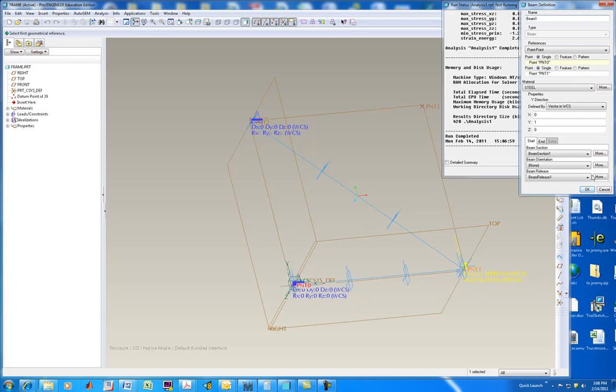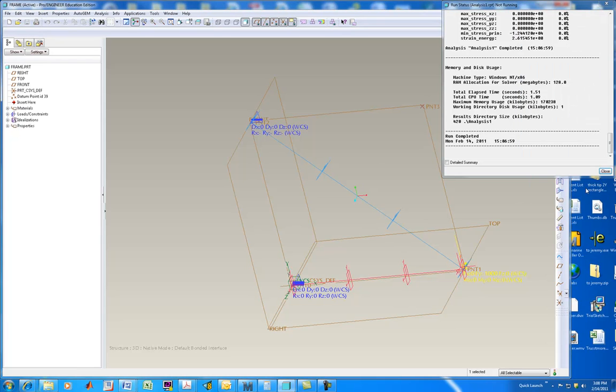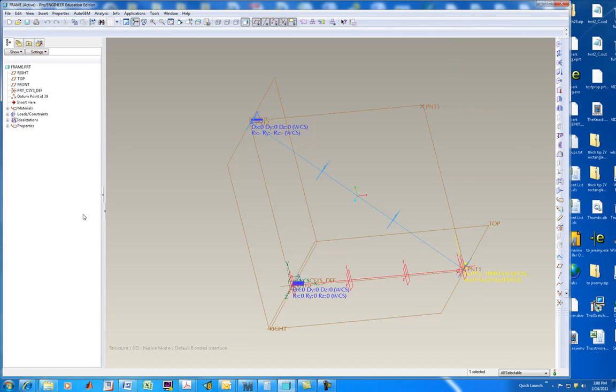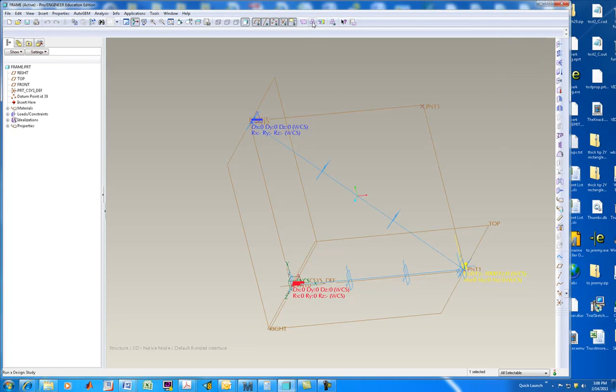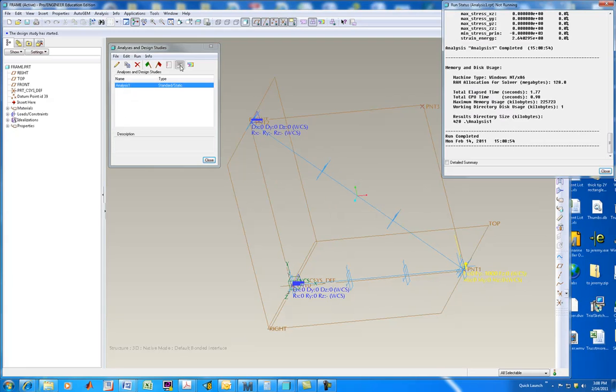And so I'm going to go ahead and set this back to none. Apparently the constraint totally overrides the beam release, and so I'll just need to go edit the constraint at this end. Right, make it red, edit definition, and I'm going to release Z rotations on this beam. Okay, run it, yes, no. The results should be done.